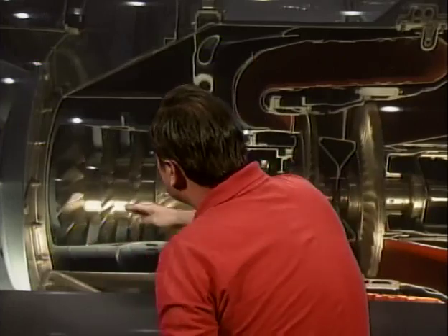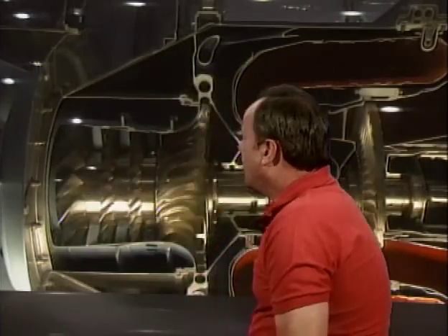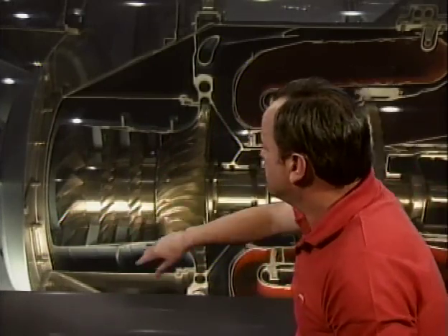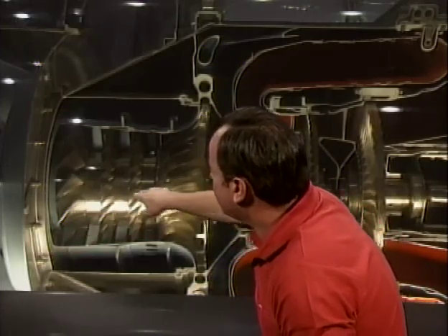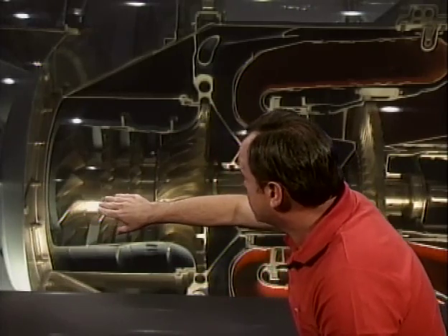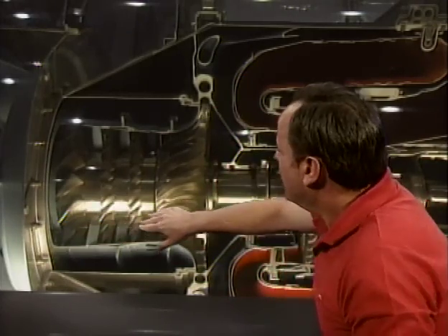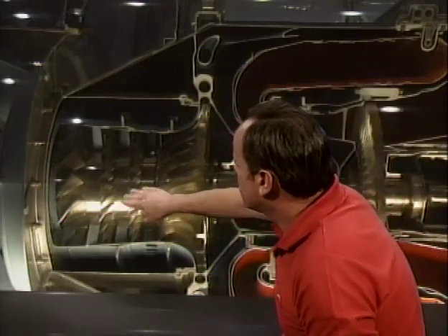And one of the things about axial compressors, if you look at these blades very carefully, you'll notice that these blades are each individual little airfoils. And they work on the principle of any airfoils. They have an angle of attack, and their efficiency is dependent on a smooth flow of air over those airfoils. Now, you could actually have these compressor blades stall. And if these compressor blades stall, that is a very bad thing, because now you have a disruption of the airflow in the engine. You have a tremendous increase in temperatures inside the engine, and that is not a good thing. So you'll want to avoid compressor blade stall.